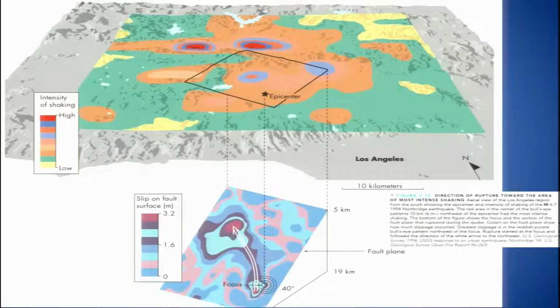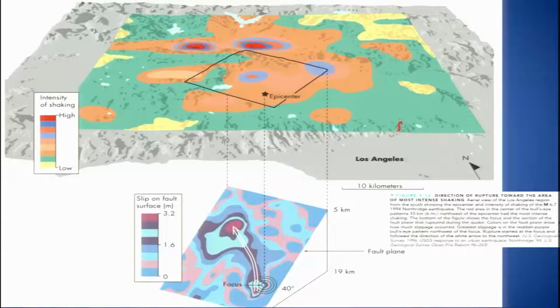Other than that, we go for seismic microzonation. Seismic microzonation is extremely important, because not all areas within a region will behave in a similar fashion, in terms of the peak ground acceleration, that is PGA, and this will depend upon the material or the site condition.